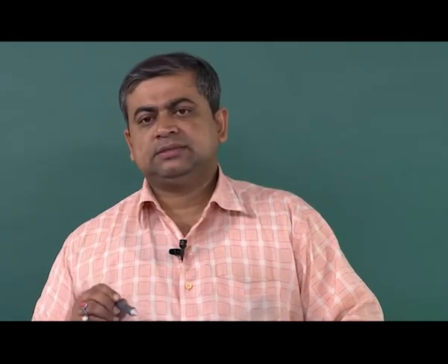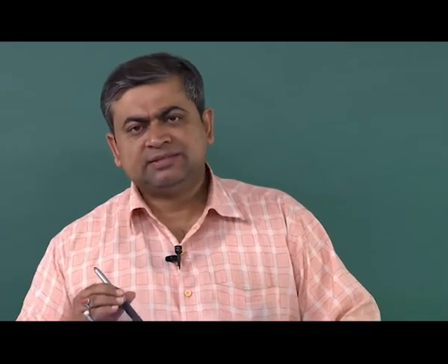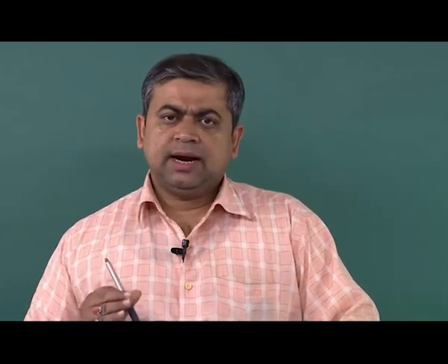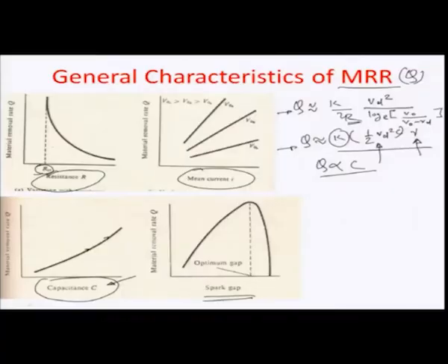So it starts at a minimum value of resistance, the critical resistance, which needs to be necessarily maintained in the inter-electrode gap so that a successful EDM operation can be carried out. If you look at this trend here, the range of resistance really starts from the critical resistance R_CR onwards, and as the resistance increases, material removal rate goes down.